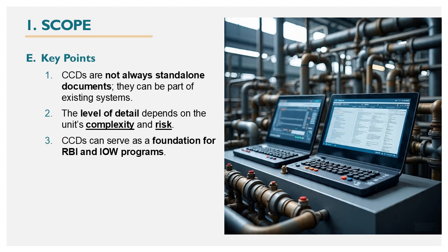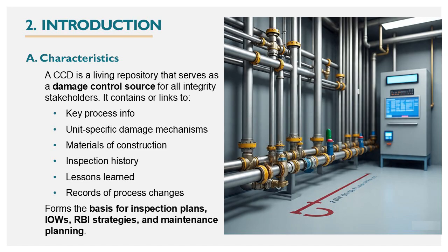Number E. Key points of Corrosion Control Document or CCD. CCDs are not always standalone documents, they can be part of existing systems. The level of detail depends on the unit's complexity and risk. CCDs can serve as a foundation for RBI and IOW programs.